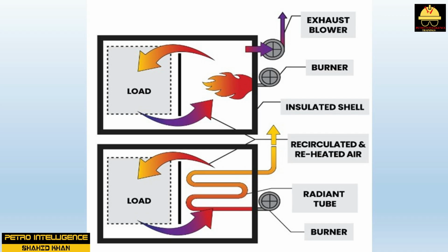This type of heater is composed of a shell and a series of steel tubes designed to transfer heat through the combustion chamber, tube, and into the horizontal fire tubes. Exhaust fumes exit through a chamber similar to an exchanger head and pass safely out of the boiler. The water level in the boiler shell is maintained above the tubes to protect them from overheating. The term fire tube comes from the way the boiler is constructed. A fire tube heater consists of the boiler shell, fire tubes, combustion tube, burner, feedwater inlet, steam outlet, combustion gas exhaust port, and tube sheet.